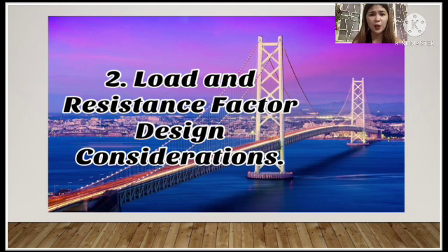So number 2, load and resistance factor design considerations. In the AASHTO LRFD specifications, the equations for computing the compression member strength are the same as those in the AASHTO LFD provisions. So refer to AASHTO LRFD 5.7.4.4 for axial resistance and 5.7.4.5 for biaxial flexure strength.